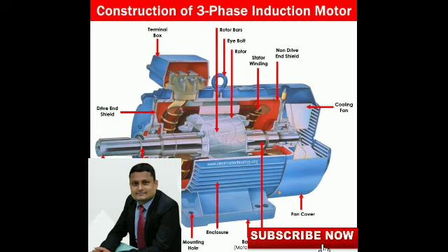If L by tau is between 1.5 to 2.0, the feature is minimum cost. For good power factor, the ratio L by tau is 1.0 to 1.3.